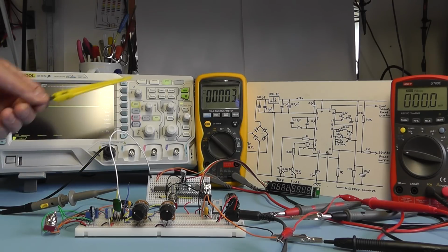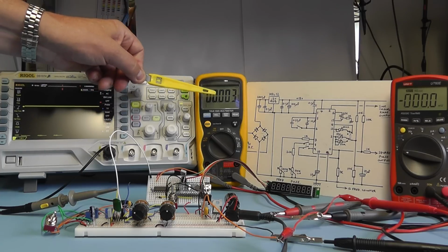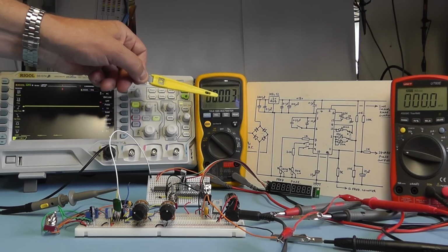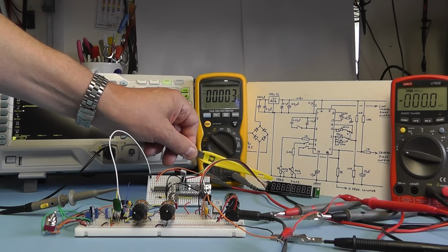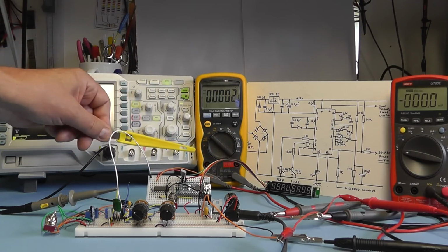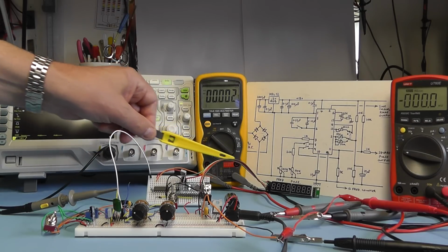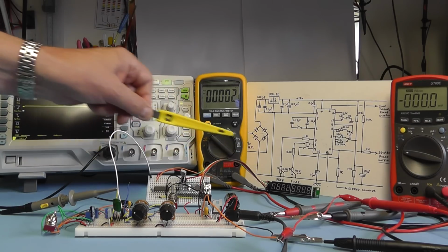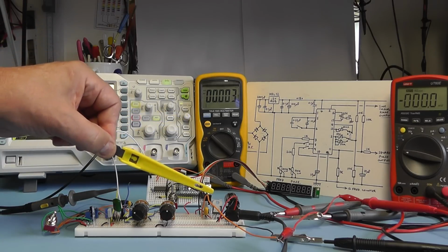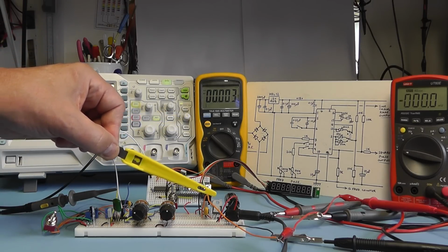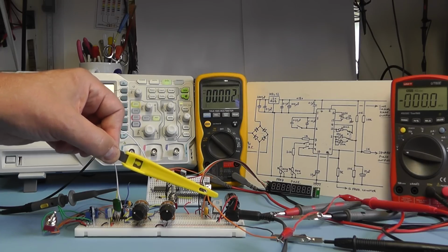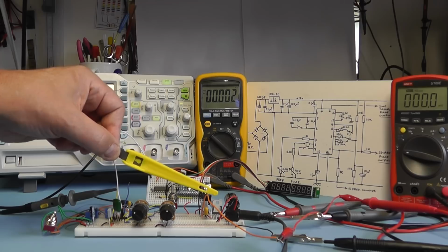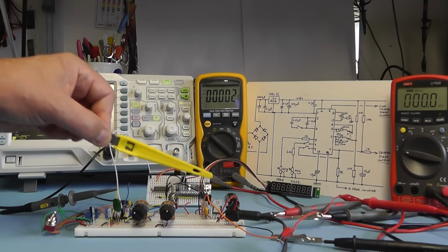Now the other thing I've done here is I've connected a current meter here to monitor the input current from the bridge rectifier, just to monitor that, because I would suspect that as we drive the 7-segment display we'll start to draw a lot more current, and I just want to make sure that if there's any issues there, and for that reason I've also replaced the 12 volt regulator IC there with a 1 amp 12 volt regulator IC rather than the 100 milliamp one that I had there previously.